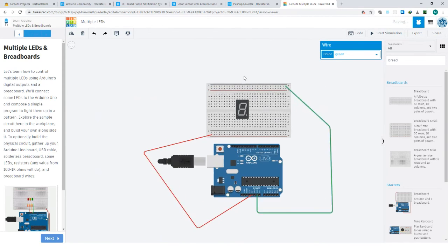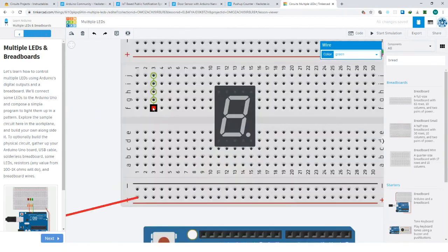And remember, we talked about the connection with the pins inside the board. You see, this row is connected. This row is also connected. This row is also connected. The same. We'll be using pin 11 there, and number 12, row number 13, row number 14, row number 15. So we know what we'll be dealing with. In our case, we said the one in the middle is the common one. So definitely we are going to take a cable from here to connect to the negative. Okay, let us put it there. And because it's a negative, we put it black.